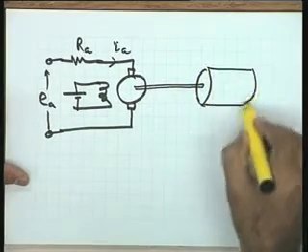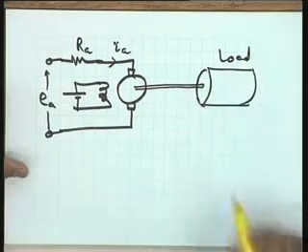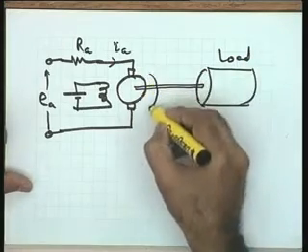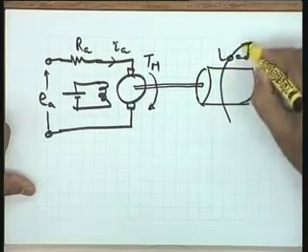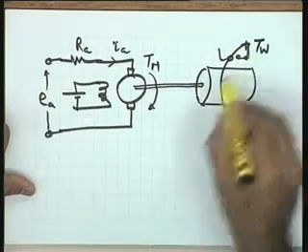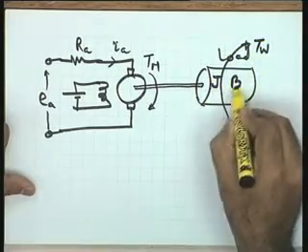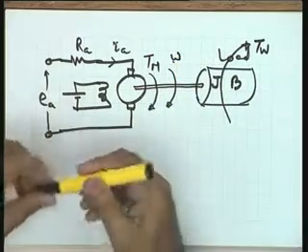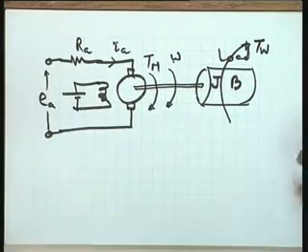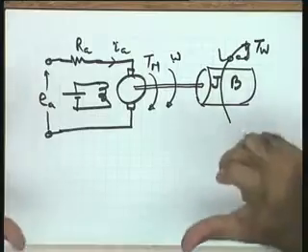and I have a load here. The motor produces a torque Tm and the load disturbance torque is Tw. The parameters of the load are J and B, and let us say the speed at which the motor runs is omega. I want you to give me the mathematical model of this system, so that the motor block in the diagrams we have used could be replaced by that block diagram model or the transfer function model of the motor. The things are known to you.